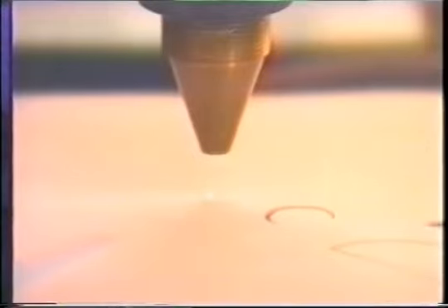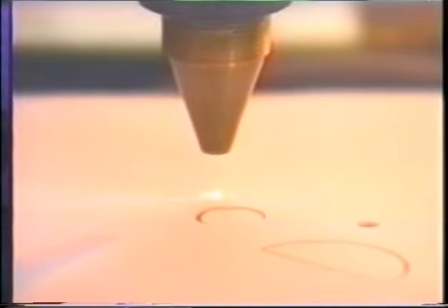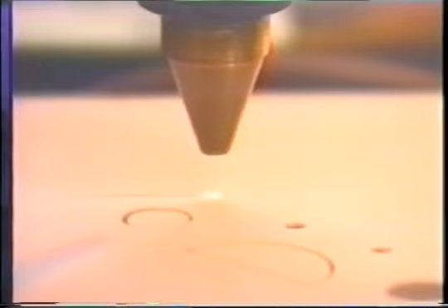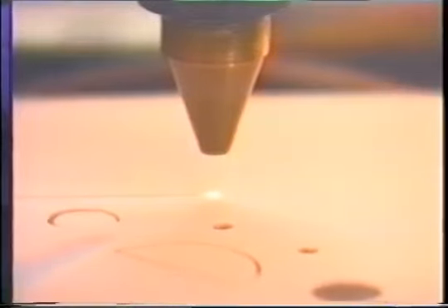In addition, this project is exploring a methodology for the automatic design and fabrication of multi-purpose robot gripper fingers based on CAD descriptions of the parts to be grasped. The system would use rapid prototyping technology to construct fingers out of rigid plastic sheets. This approach would facilitate the concurrent design of robotic grippers and product components.